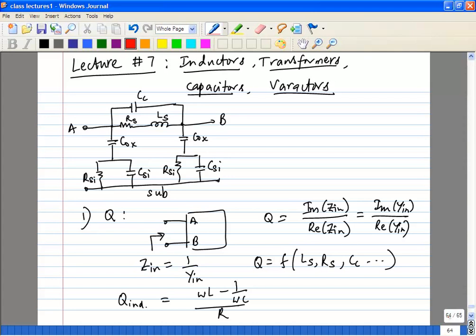That metal, and you ground that metal line, metal plate, that is going to shield your magnetic substrate from all magnetic fields, right? And because it's a perfect conductor, it actually gives a return path for the magnetic field, but there are no eddy current losses because you're assuming it's very, very low resistivity, right? Okay, so now if you do that, what do you think will happen?